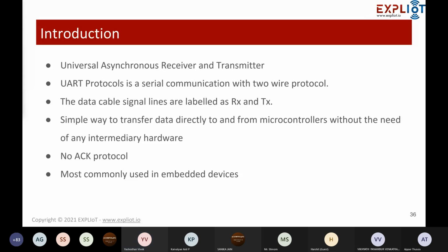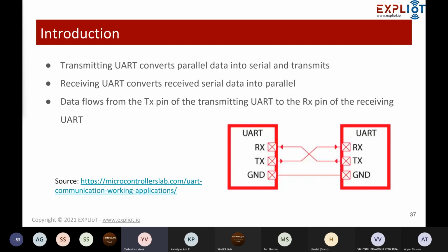communicating over there. So this way, when you have the UART communication, you have basically three major pins, right? Which are transmit, receive, and ground. The ground is basically the reference point. If you are measuring some voltages, ground is always a reference. And here, let us consider this particular pin as transmit, and the left part is a transmitter, the right part is a receiver.